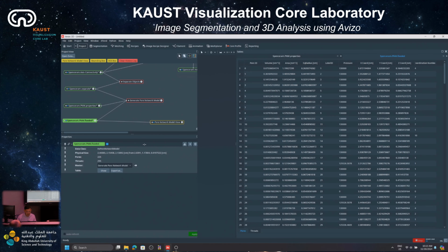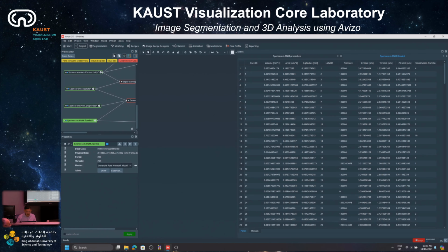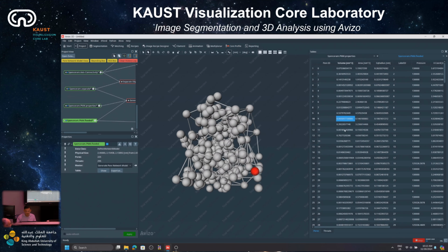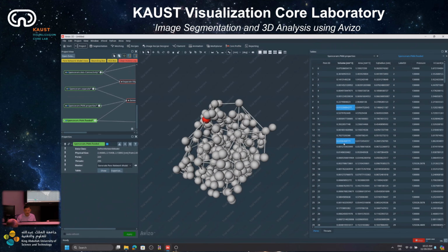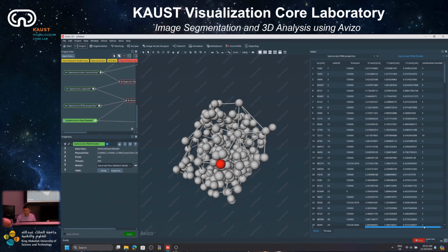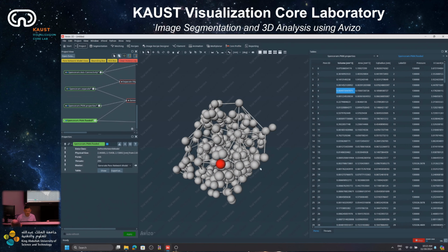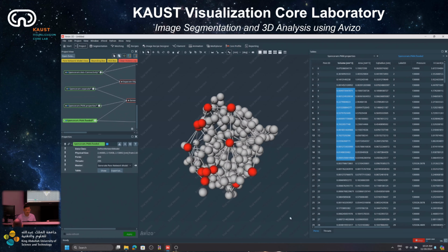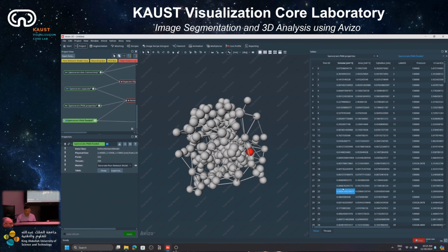And go back here to see quickly. By default, pore: if you just select one of them, it highlights where the pore property is. So you have volume, area, equivalent radius, and some kind of pressure and flow rate per second later. You can select even a few of them, click, and you can see where it's highlighted.